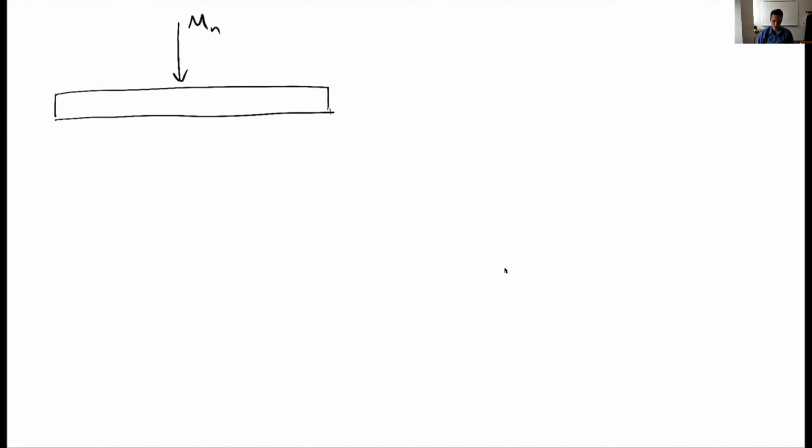I'm just moving it along. Because it's inviscid, the fluid around it isn't going to be dragged with it, so it doesn't really know that's the case. Okay, that doesn't really matter. But because it's moving, the relative inflow into the wing is going to look like this, right? There's going to be some tangential component. So this is my actual free stream component.